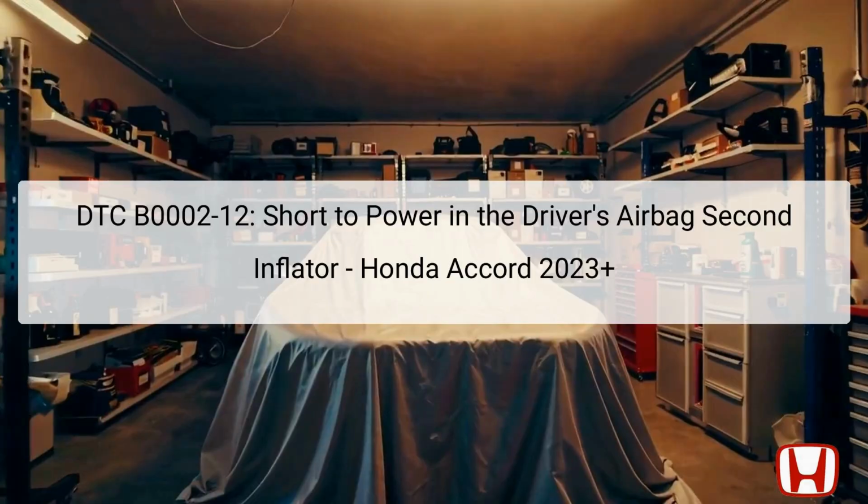This presentation focuses on Diagnostic Trouble Code B0002, indicating a short-to-power condition in the driver's airbag second inflator of the Honda Accord 2023 and newer models. This DTC is generated when the SRS, or Supplemental Restraint System, unit detects a voltage level that's higher than acceptable on the detection line.